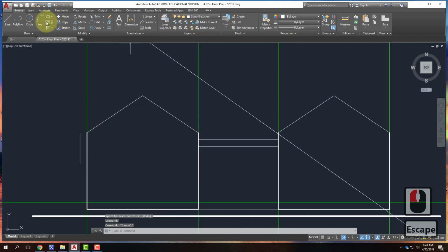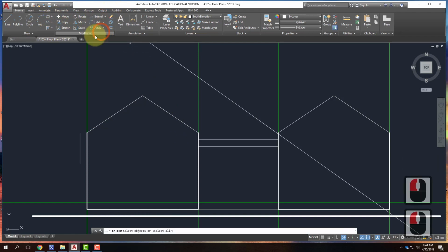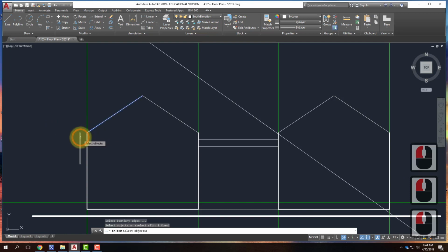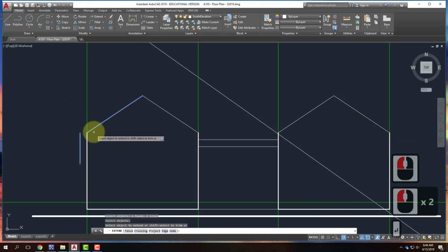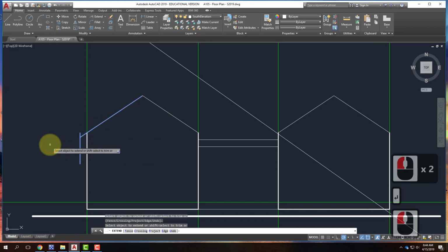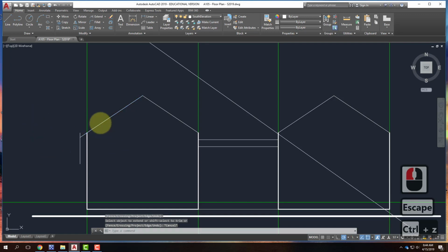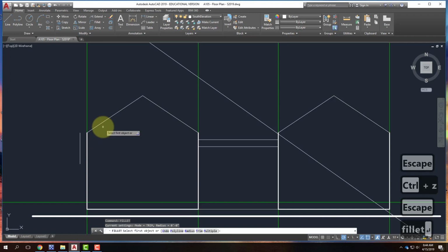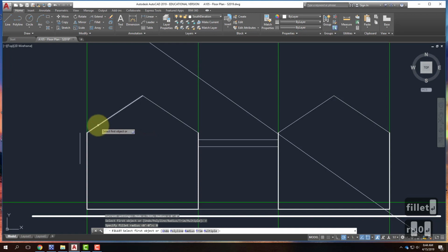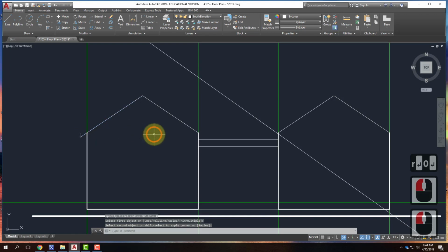I'll use the extend tool, which is available underneath the trim. There's extend, this line, and this line. I'll hit enter. And I want that line to go out by a foot. That's the easiest way of doing it. The other solution would be to do it with a fillet, like I did before, with a radius. So I type R for radius of 0, and then I could connect this and that at a point. So I'm starting to create this.